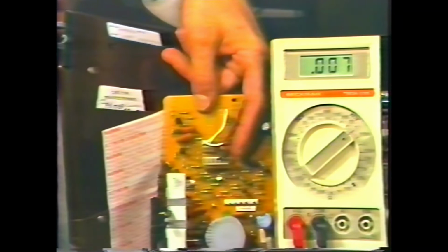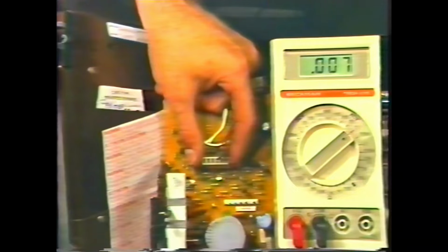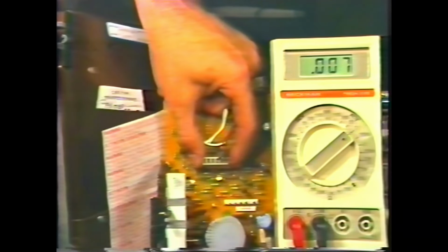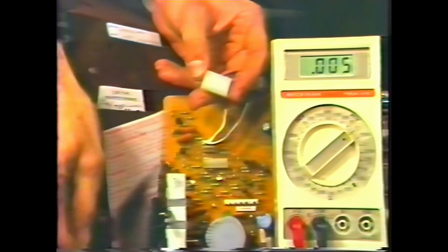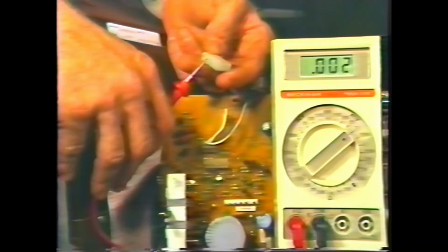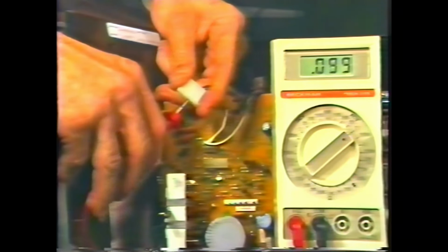This video connector carries the video signal from the computer, and we can check with our meter and see if this video signal is present by inserting the meter lead into the connector. The changing voltage that we read on the meter indicates that the video is present. The higher the voltage, the more of that particular color is appearing at that time on the front of the screen. In this case, we definitely have video.